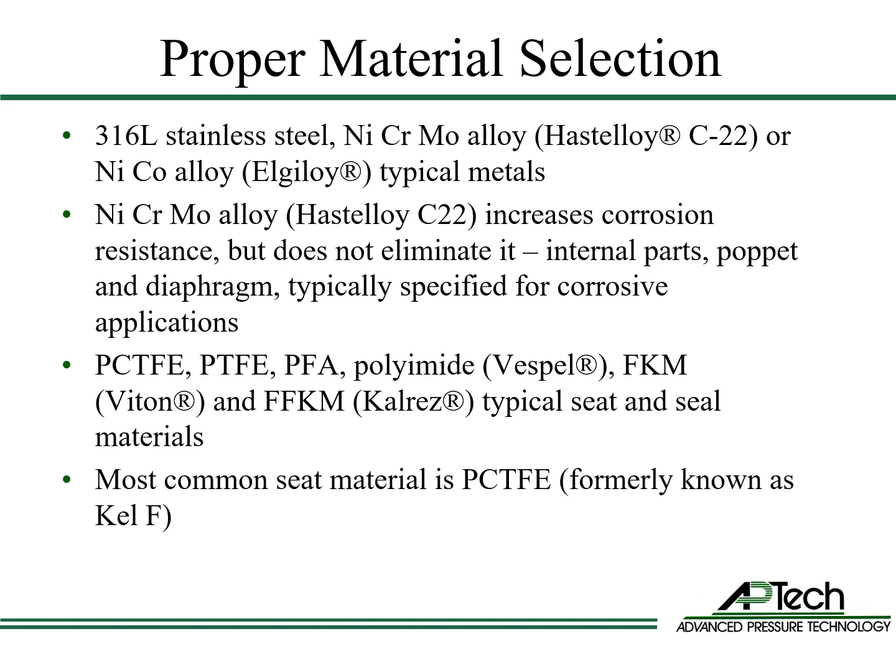Seat and seal material options are polymers such as PCTFE, PTFE, PFA, Polyimide, FKM, and FFKM. The most common seat material is PCTFE.